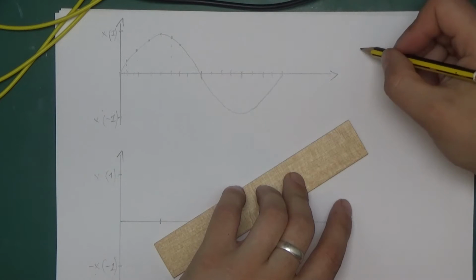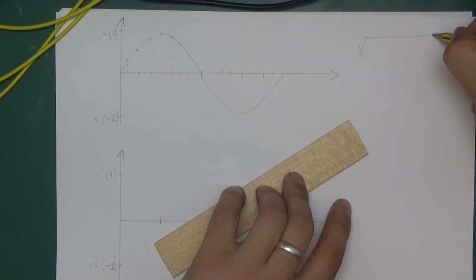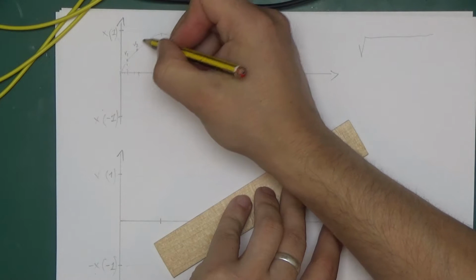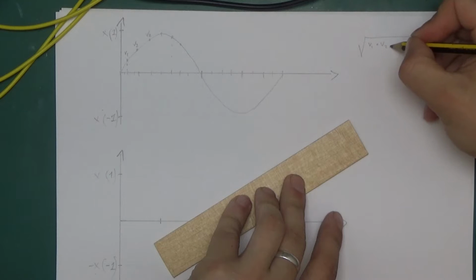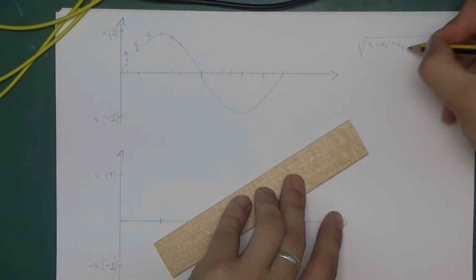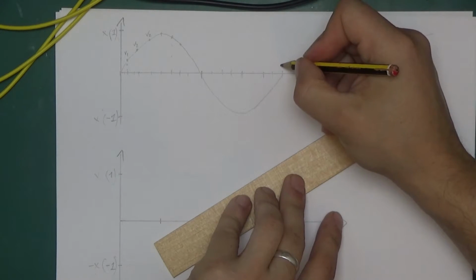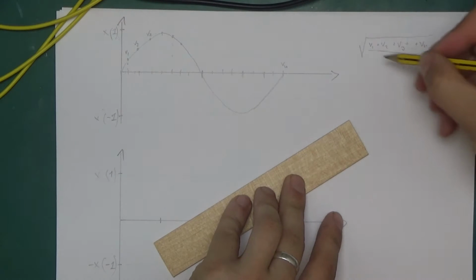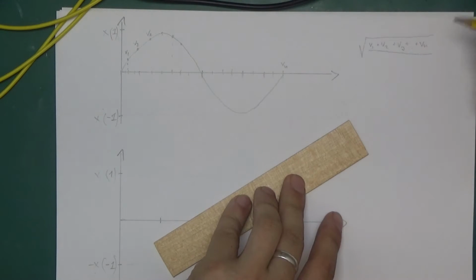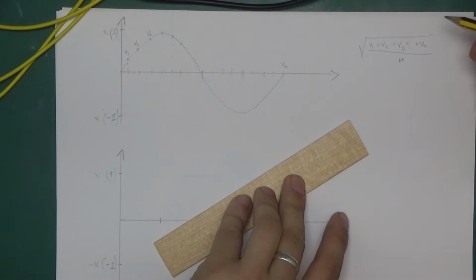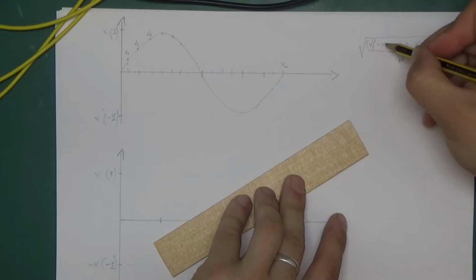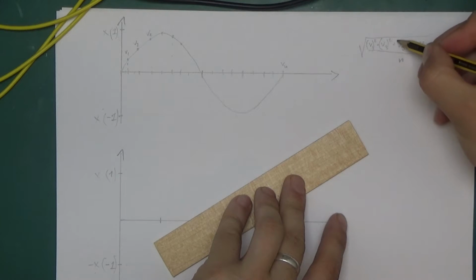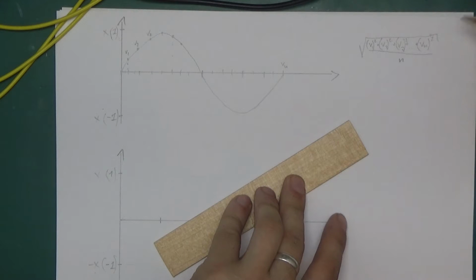The formula for that would be, it's a root, that's the root in root mean square, of V1 squared plus V2 squared plus V3 squared and so on up to Vn squared, divided by the number of measurements that we took, so divided by n. So that's the mean value, and then there is the square. Each of the voltages has to be squared individually before being added up. That is the formula for approximating the RMS value.